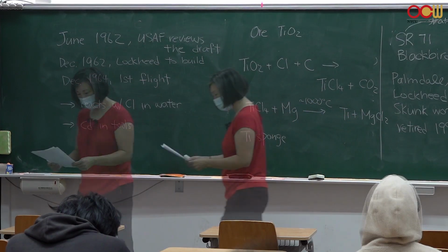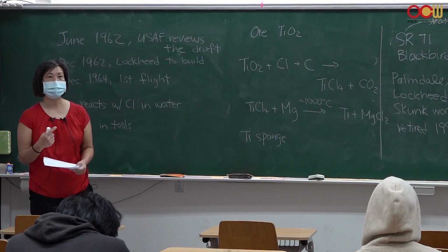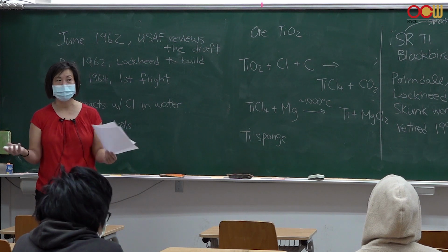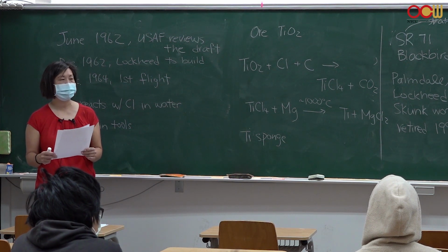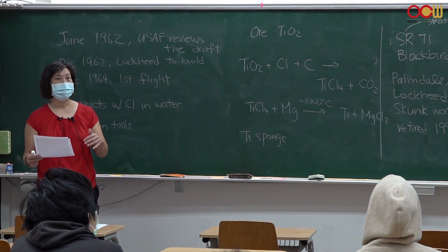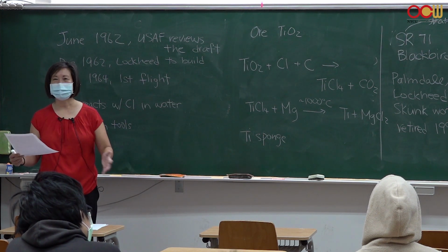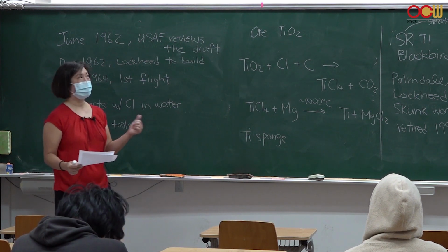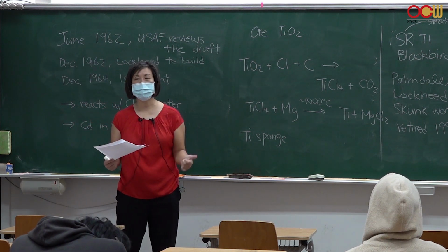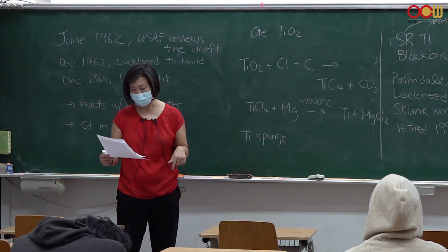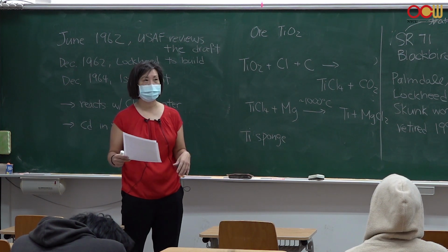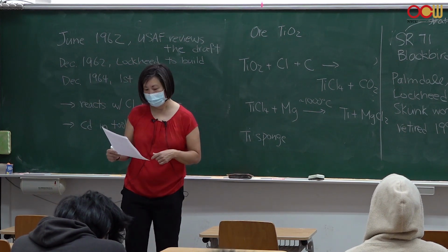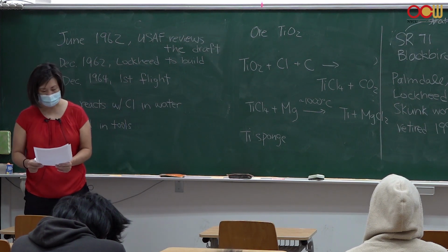And the manufacturing, also, because titanium is so strong, the strongest tool that they had to work on metals at the time could only provide up to 20% of the forces that were needed. So they had to build brand new machines that can press the titanium with higher force. So lots of things like that. They were finding that the drill bits, because titanium is so hard, the drill bits were becoming dull, and that they could only use them 17 times before they had to throw away each of the tool bit because it was dulling. Okay? And so things like that they had to really work on.